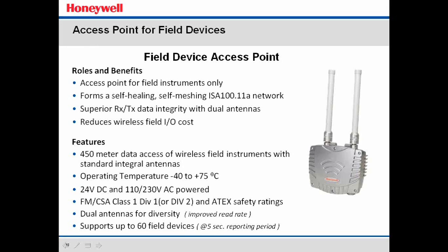The system limitation, and I don't think that's in here, I'll talk about it real quick. The system limitation for transmitters, when I talk about system, I'm talking about the WDM, the Wireless Device Manager, which controls the system. Each wireless device manager can handle 100 transmitters. It doesn't matter about the update rate. It can handle 100 1-second update rate transmitters or a mixture of update rates across the network.